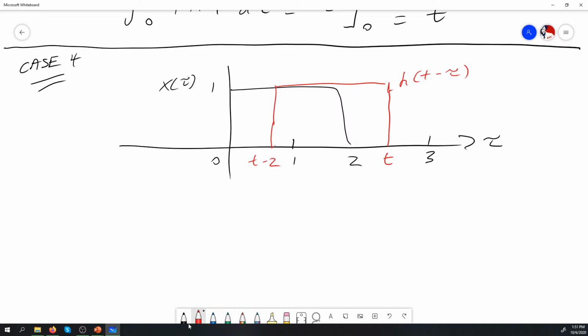So for this particular convolution, there will be no changes in the equation x and h, because they're always going to be a value of 1. But when you start doing convolution with piecewise continuous signals, you want to see that the equation will keep on changing accordingly for where you have your overlaps. So because we slide our h of t minus tau signal here again by 1 time unit, our overlap exists for this part here.